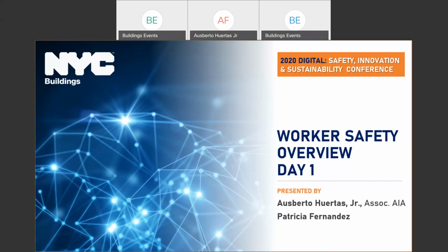Let's see what else we have. A lot of these questions are mostly the same. So housekeeping plans: there are no housekeeping plans that are required by law. We may mention a housekeeping plan as best practice, and just keep in mind that it's something that should be well attended to ensure worker safety and site safety throughout the job itself. If you look at Chapter 33 in the building code, it does talk about general good safety practices that should be followed. So keep that in mind.